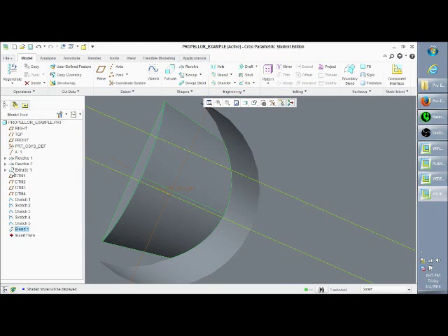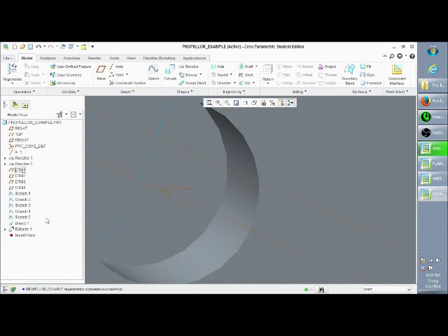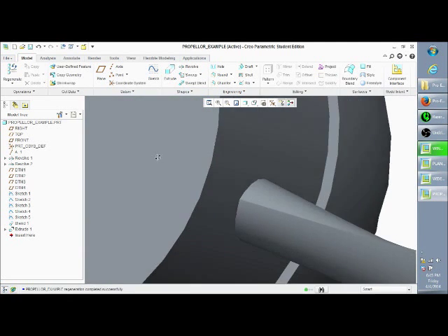To fix this is just a layering issue. Since we have all these items that are all connected to this, you can either select this one, hit shift, hit this, and then click that one, and then drag them all up so that they're in front of this extrude function, or you could just drag it all the way down to the bottom, wait for it to regenerate everything, and notice that it's not there anymore, which is exactly what we want.